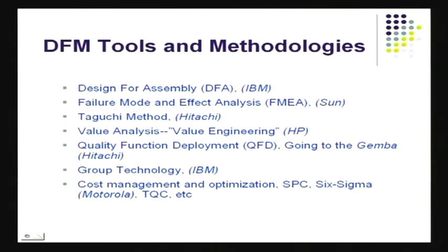A design or a process or a product can fail many different ways. And before you go into commercial production or before you commission the final product, you've got to make sure you've done FMEA. You've tried to predict in what different ways, in what different modes can a product fail. You also have to make sure when you're doing this, you look at the effect, and you look at a couple of things. One, the first thing you look at is how likely is it going to fail? What is the likelihood of a particular mode of failure? In what different ways can it fail? That is mode. Then you got the likelihood of failure. Then you got to look at the impact of that failure.